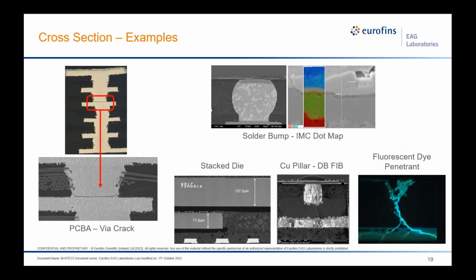If we go to the next slide, we have a few pictures that show some of the things I talked about. The very left image is an FR4 copper stack via, done with a metallurgical mechanical cross-section. But this crack in the via wasn't actually visualized until we cleaned it up and removed the smearing artifact. Copper, as you know, is a softer material, so when you're polishing and grinding, it backfills the crack and smears across it, which may prevent you from visually seeing the crack.